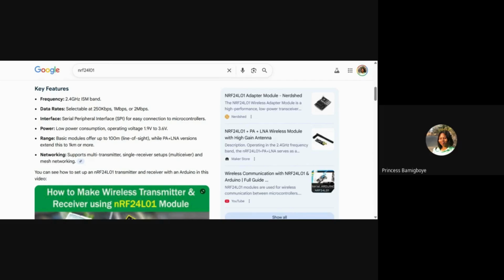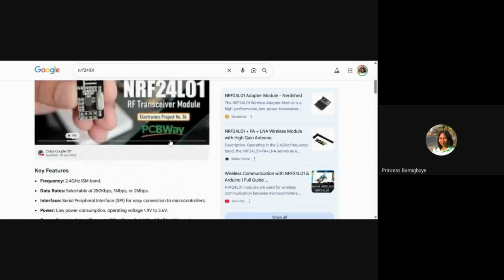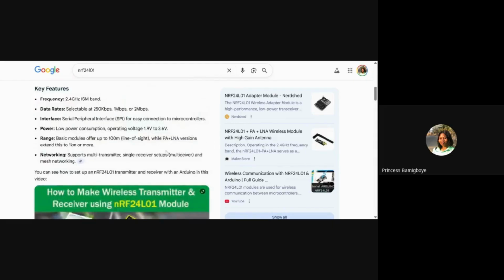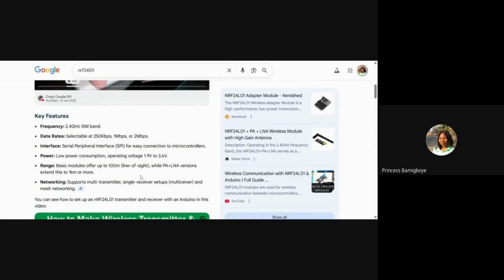and then it doesn't work properly, or it's too much and then it burns. You don't want a situation like that. So always make sure to check the operating voltages, operating current, maximum power consumption, everything that you are going to need for the component, so that they will not burn, and you know which pin to connect them to.